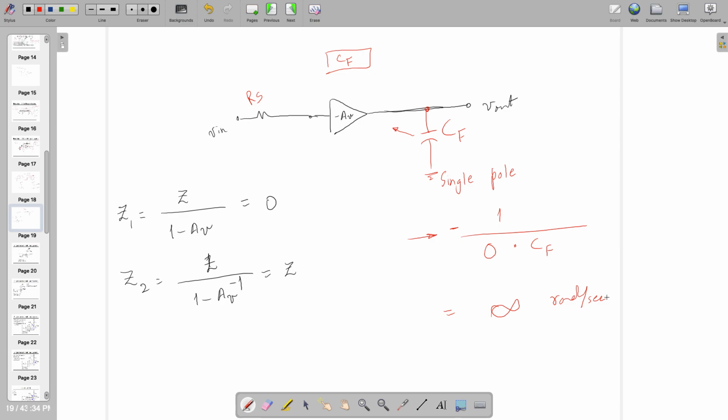However, when we are going to use this, you will see that of course there will be some impedance. That impedance might be 50 ohm or whatever is there. You need to keep that, and it will have some finite number, not infinite number. Maybe we will apply this theory on the amplifier stage, and we'll understand how it's impacting in terms of poles, in terms of zeros, and how it's impacting the overall stability of the system. So if the system is not stable, make sure that it has to be stable by some pole splitting or pole placement technique, which we are going to study in maybe further lectures or maybe further courses also.